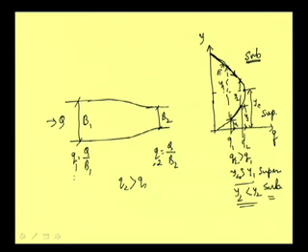Well, now what about the flow depth? If the channel is like this and a subcritical flow is approaching, coming like that, in this narrow portion normally we have a feeling that when the width of the channel is reducing, depth will increase, because width is reducing with Q remaining the same.